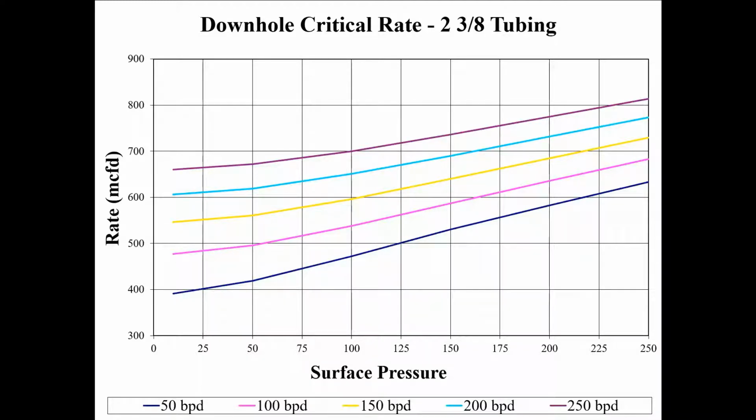A standard cubic foot of gas at standard conditions is subject to higher pressure at the bottom of the well and will have a lower velocity than the same volume at the wellhead, where the pressure is lower and velocity is higher. The critical velocity lines at the wellhead and the bottom hole pressure will be close together for shallow wells with higher line pressures, and when there is little differential pressure across the wellbores.